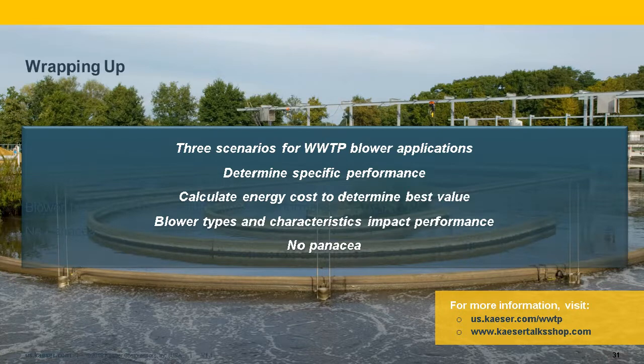So it's always important to, again, create your model, get your blower data, apply the blower data, make your evaluation. From your evaluation, you can evaluate your investment cost versus your return on investment and select the blower manufacturer and blower technology which best suits your project needs.